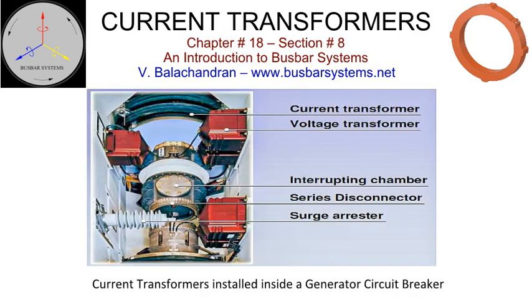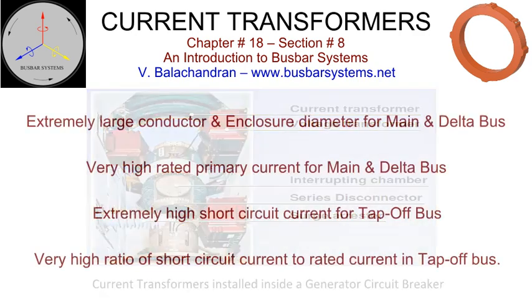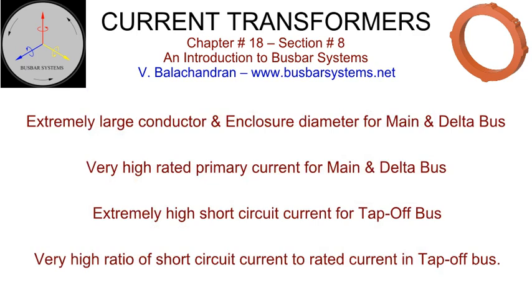These current transformers can be either installed in the run of the isolated phase bus or integrated with any of the major equipment. They can be installed on the phase and neutral bushings of the generator, as an oil-immersed bushing-mounted transformer inside the tank of generator transformers and auxiliary transformers, and on either side of the generator circuit breaker by the respective equipment manufacturer.